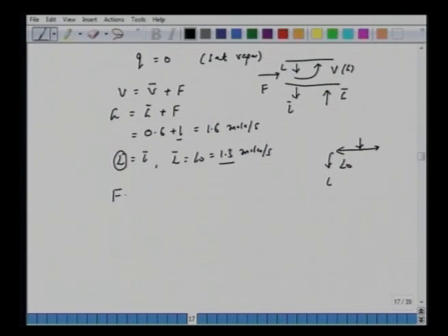We have the overall balance F equal to D plus W. F is known, but D is not given, W is not given. We can write the species balance F XF equal to D XD plus W XW. Again, XD and XW, the compositions of the distillate and the bottom products, are not given here. XF is of course given. So it looks like from these two equations we are unable to determine the rest of the quantities.